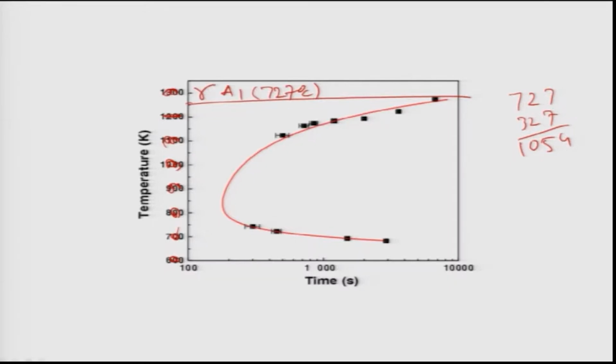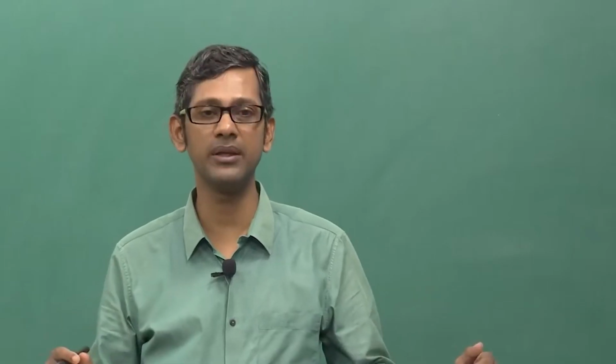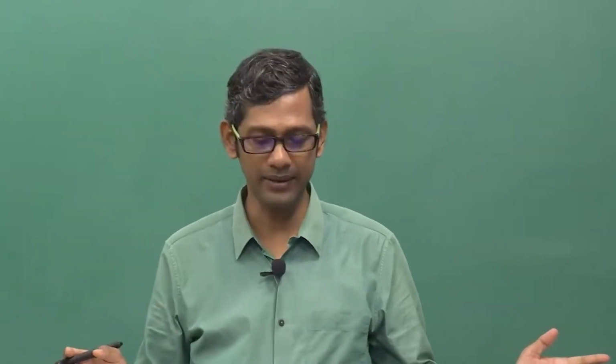So for the pearlite, when it is close to 720 Celsius temperature, undercooling is low. So therefore nucleation and growth is very slow, correct. But remember, diffusion is also very fast at high temperature. So therefore what will happen, you will have a smaller number of pearlitic colonies, fewer lamellae present in the microstructure, but the lamellae will be thick because diffusion of carbon is high at high temperature.